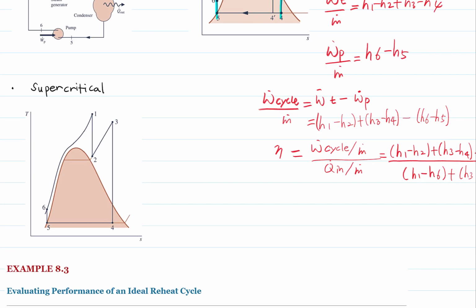Now let's consider a supercritical working fluid. In the boiler, it creates the supercritical vapor at high pressure and high temperature above the critical point. When it becomes supercritical, there is no distinction between fluid and gas. It provides a very high temperature of the working fluid, thus increasing the thermal efficiency. As the pressure and temperature are so high, the components of the Rankine cycle must be built to withstand the extreme conditions, and it can be quite expensive.